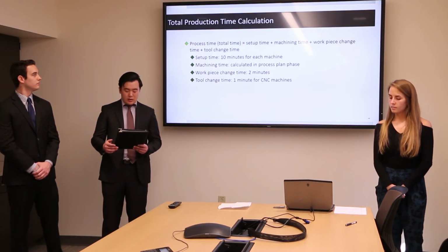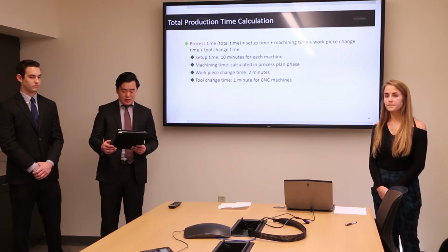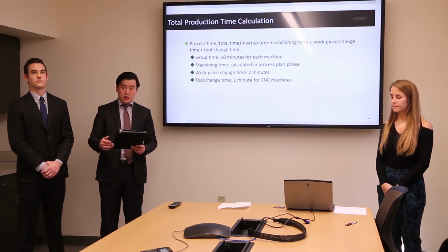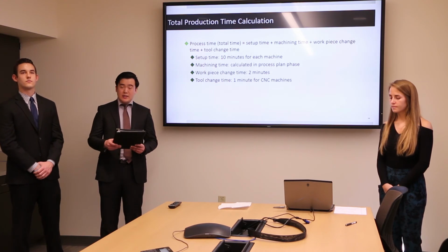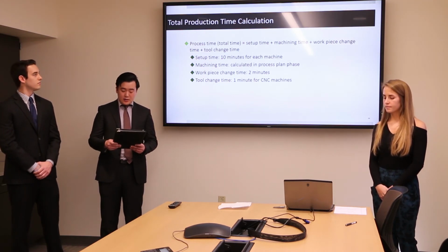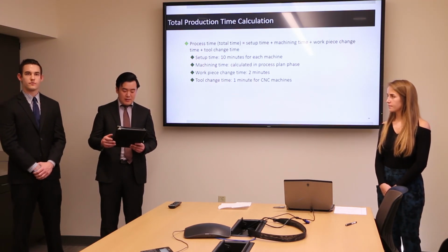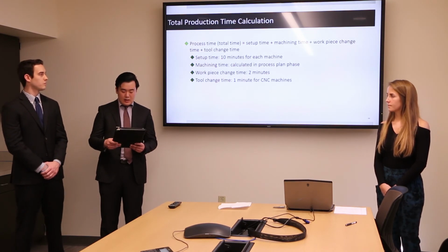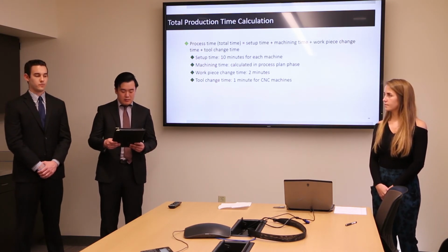The machining time is already discussed in the process plan. It can be directly used in finding the total manufacturing time. Workpiece change time is 2 minutes and counted each time for mounting a new workpiece on the bench saw, CNC lathe, drilling press, and the CNC milling machine.